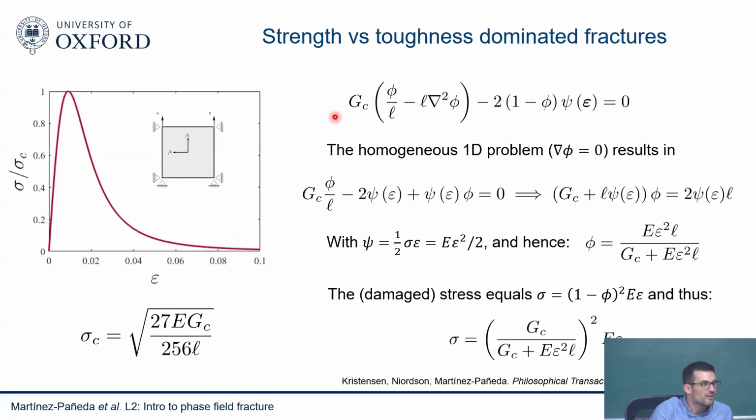I think there was a question there. Say I want to repeat this for two materials, steel and glass. As I understand it, G is a natural consequence of the simulation of the deformation of the strain energy. Yes, so Gc will be the input. For steel, I'll use, I guess, 1,000 kilojoules per square meter. For the glass, I would use 3 joules per square meter. Then in that case, what would be the value of L?